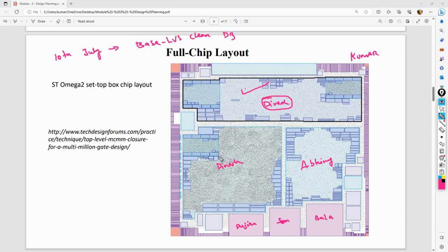Then I would run my full chip activities and full chip sign off checks, and check whether everything is clean at the full chip level, excluding your block. What that would ensure is that the moment your block is available, I would have to redo everything, but I would have already finished all the other blocks.